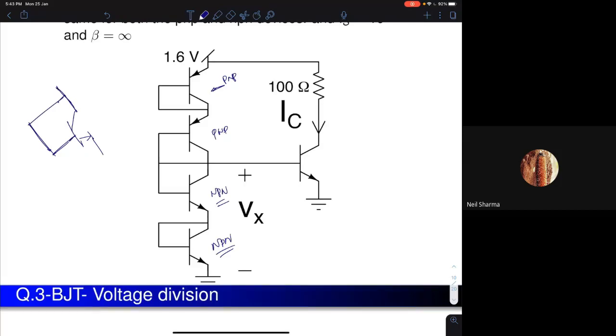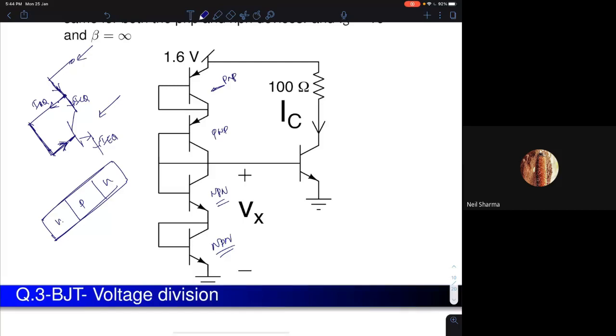See, once you short circuit your base and emitter, base and collector together, the current which will be flowing here, the base terminal also will take in some current. If it's a 3-terminal device and I directly short it, then I can directly see that this is emitter current, the base current will flow through the base, and the collector current. But as far as the external world is concerned, this will look like a single terminal which is carrying both collector and base currents.